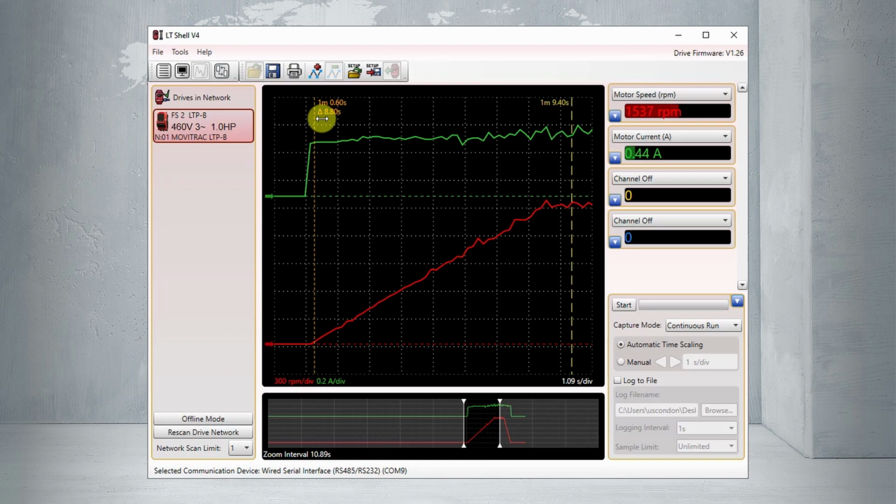And I look at my delta value right here and 8.8 seconds. So maybe actually the cursor really should have been more like here, I guess. 7.9 seconds. There we go. That actually is pretty close to 8. So you can see we're able to confirm the ramp value.